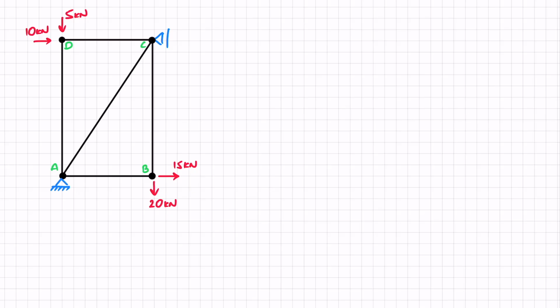That means, first thing, deciding what the supports are and what forces we need to find for the reaction forces. We can see here that at point A, we've got a pin support. So let's draw in AY and AX. And we can see that we've got a roller support, only this time it's at a 90-degree angle to what we had before in beams. That means that this is the direction of the reaction, and it is CX. Now, this is a truss. Those black dots are hinges, but since we can see that we have three reactions to find, we really don't need to worry ourselves about what the structure is.